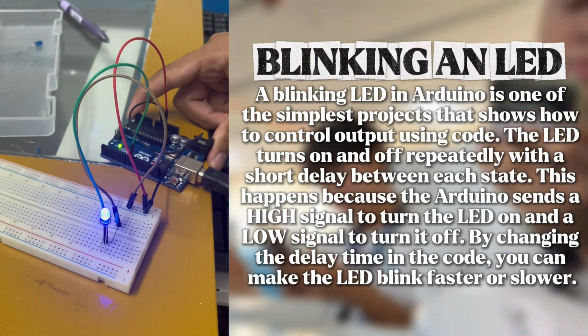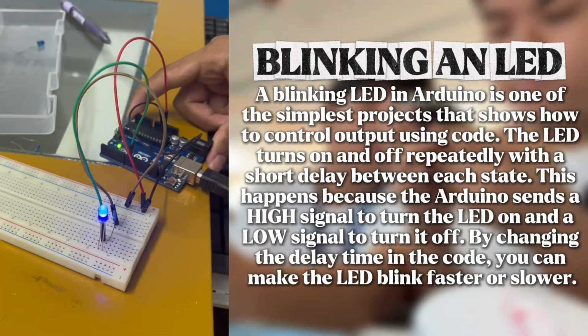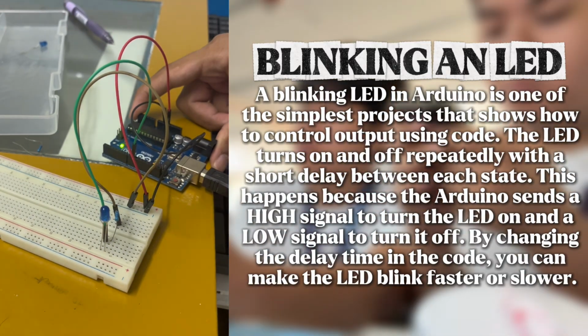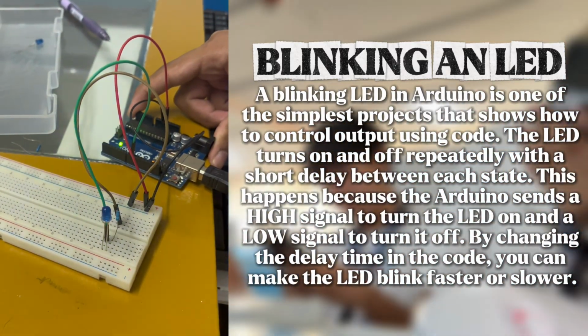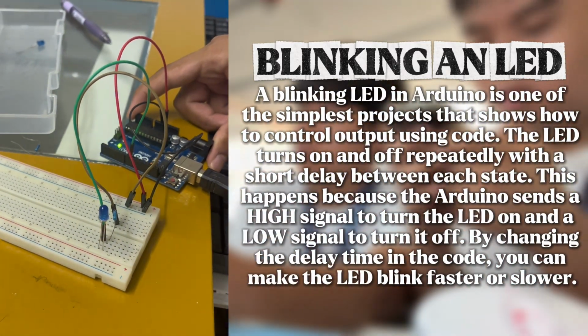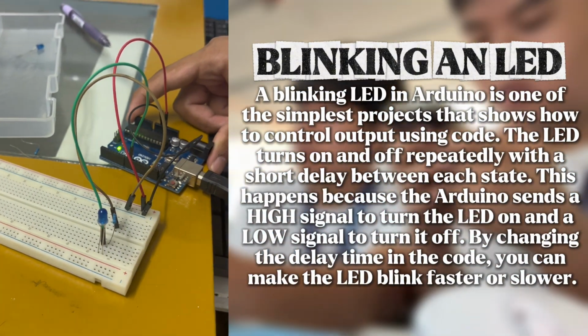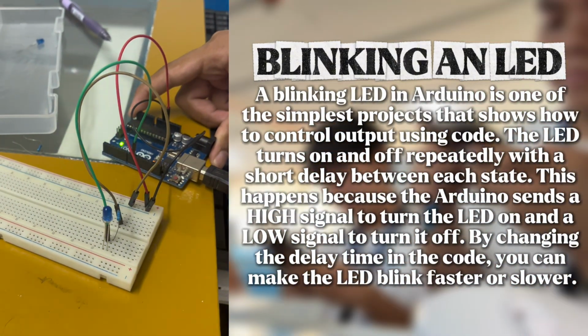A blinking LED in Arduino is one of the simplest projects that shows how to control output using code. The LED turns on and off repeatedly with a short delay between each state. This happens because the Arduino sends a high signal to turn the LED on and a low signal to turn it off. By changing the delay time in the code, you can make the LED blink faster or slower.